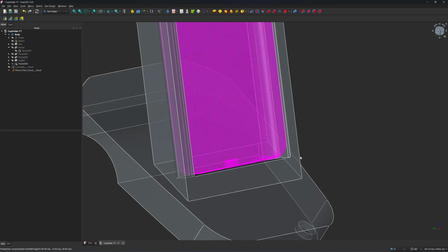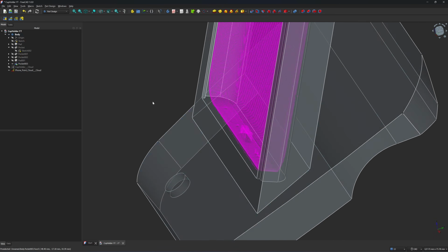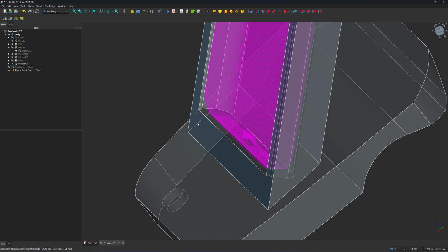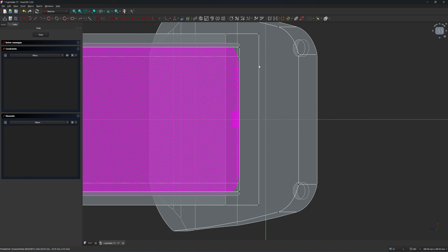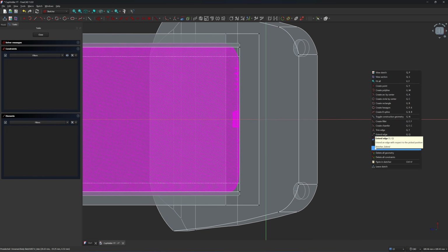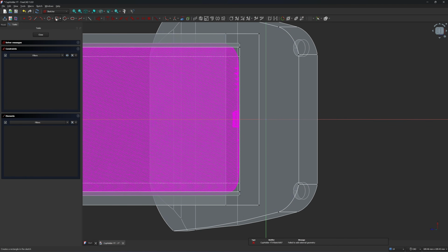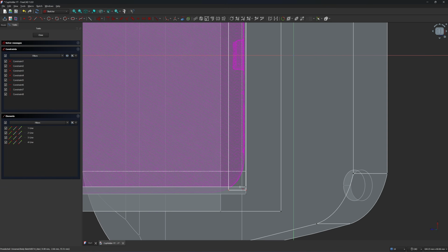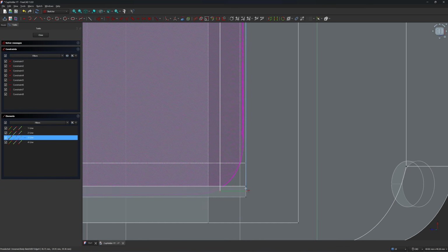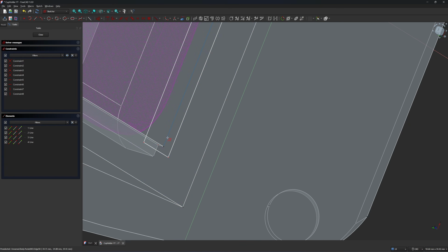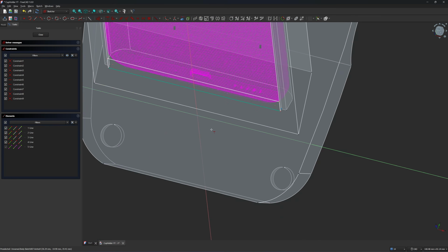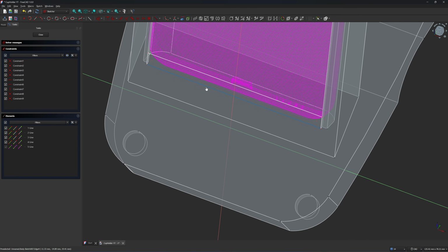Next I'm going to create a small wall here. I think the thickness 1.2 millimeter. So I create a sketch here on this plane, and I'm going to create external geometry. Create a rectangle, and I'm going to snap this line into create external geometry. Okay, snap this point to this point. Right, I'm going to do the height.